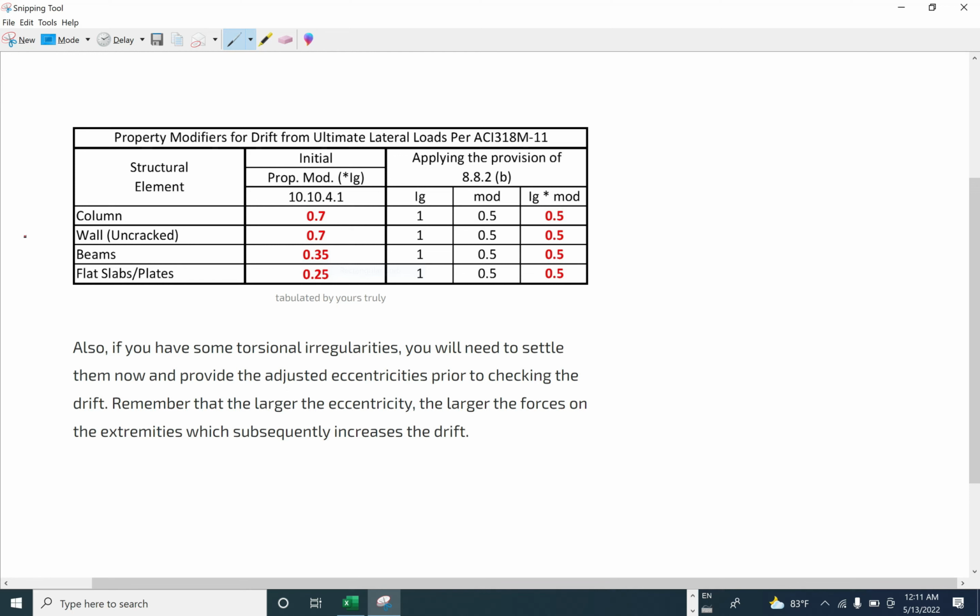You should run the analysis of your model and check the tensile stress on the surface of the member. If the tensile stress occurs or reaches the limit, you can consider it a crack section in terms of the force.